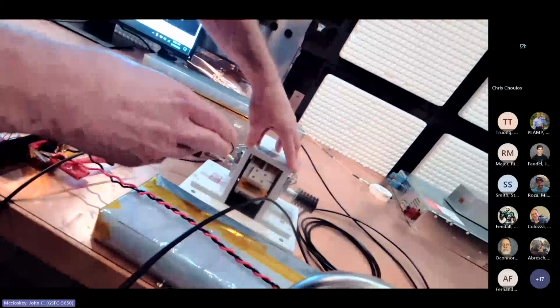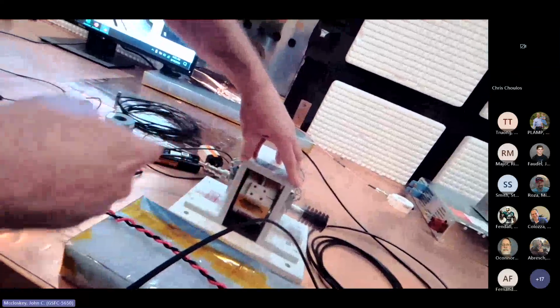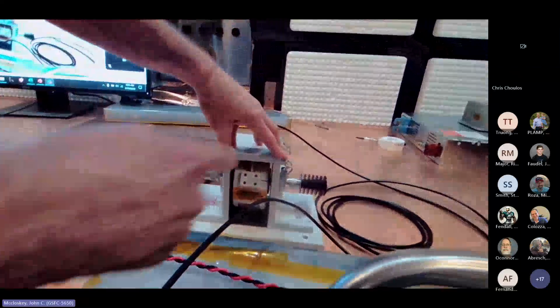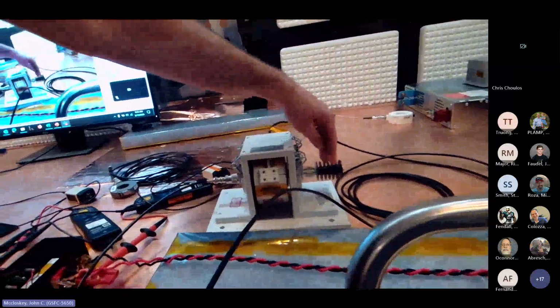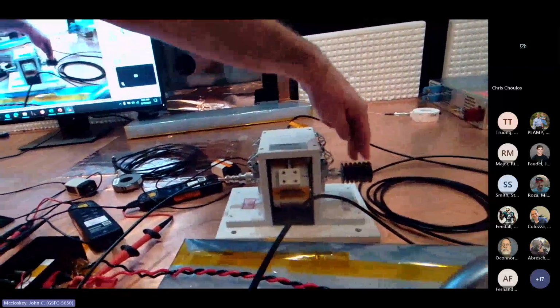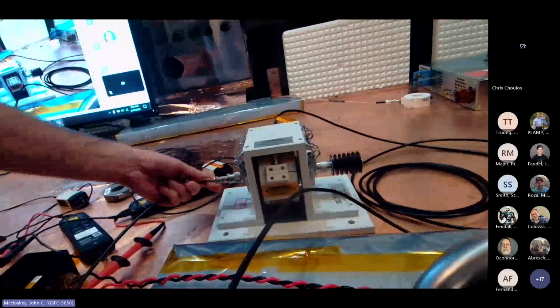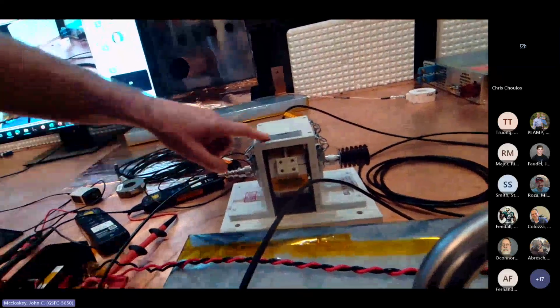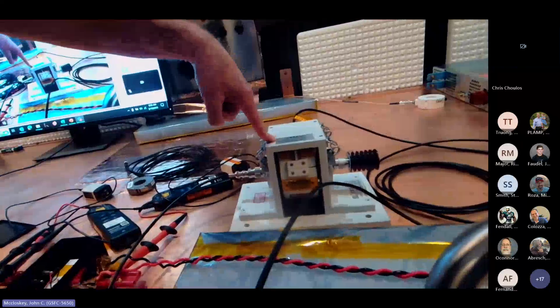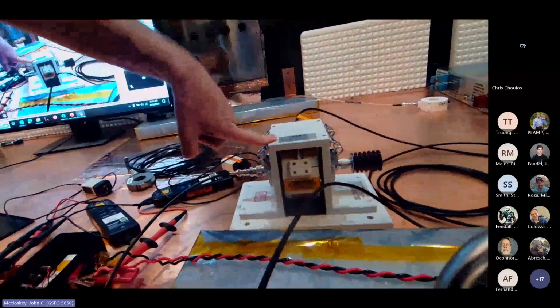But for the purposes of this test method, we need to think of them in series because you're inducing a current in the loop. So you're dropping half the potential across this 50 ohm load and half across your measurement device. So what you're measuring is half the total induced EMF in your loop. That's a crucial point there too.